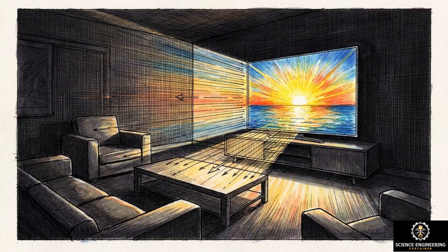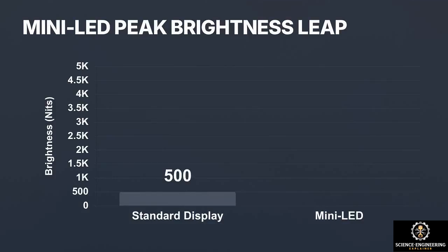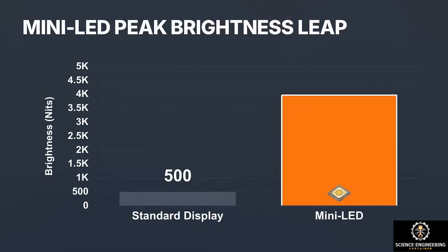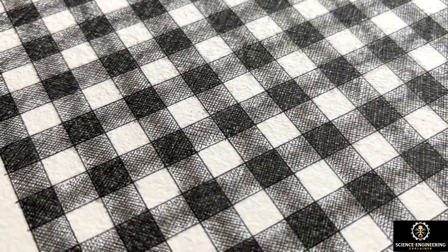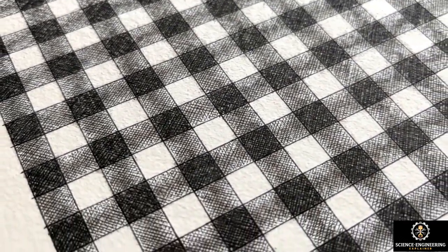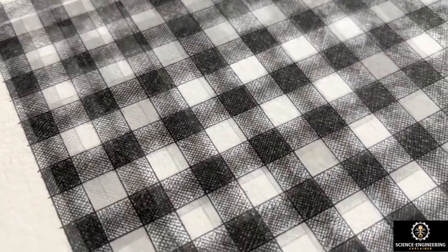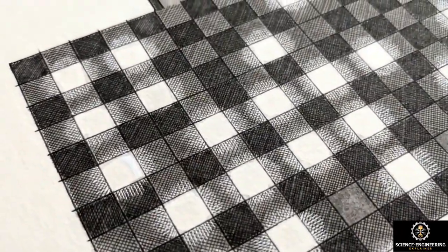By keeping a dedicated backlight system, Mini-LEDs can still pump out searing peak brightness, easily pushing up to 4,000 nits to make bright daylight scenes and specular highlights highly realistic. By utilizing thousands of localized dimmers, Mini-LED forces an older technology to produce both deep blacks and blinding highlights.